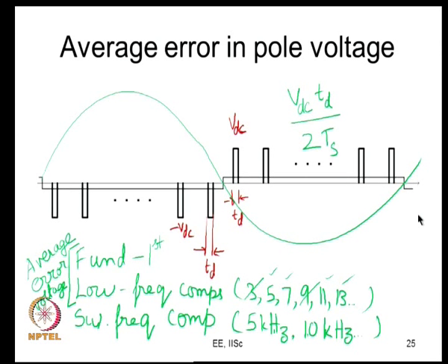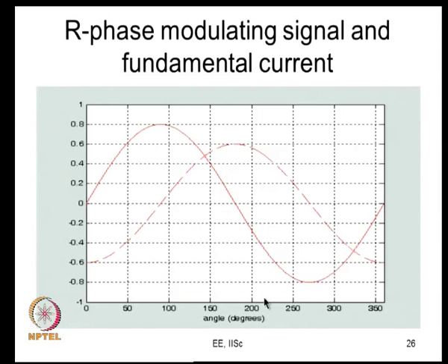That square wave contains all the fundamental and the low frequency components which are present in that now. So, let us look at this analysis. So, what are we going to do here? So, this is some amount of current that is flowing here, alright. So, there is going to be some amount of error voltage. How is that error? This error is going to be negative. There is some negative error voltage when the load current is positive and vice versa.